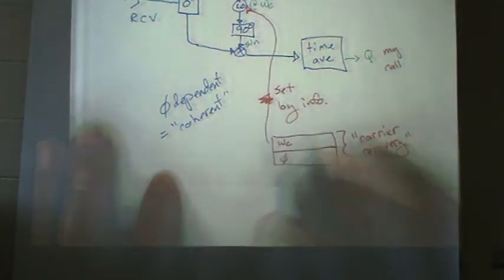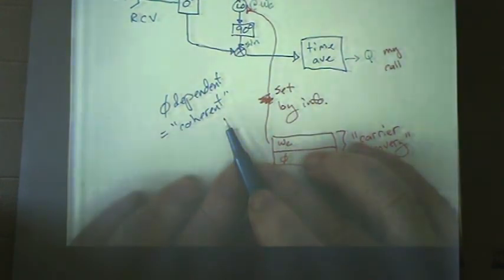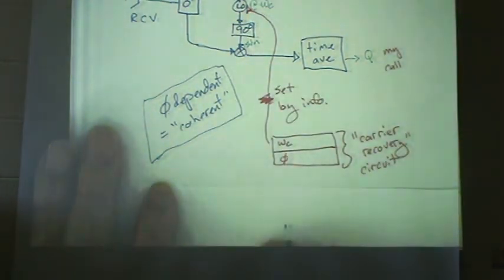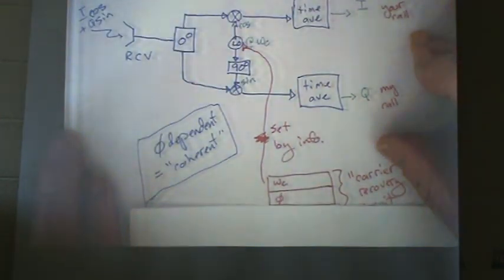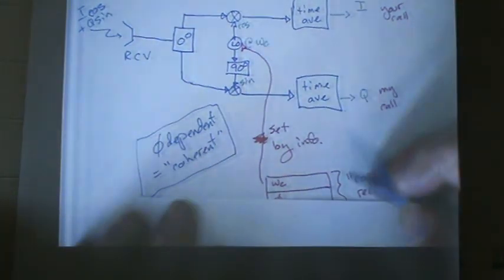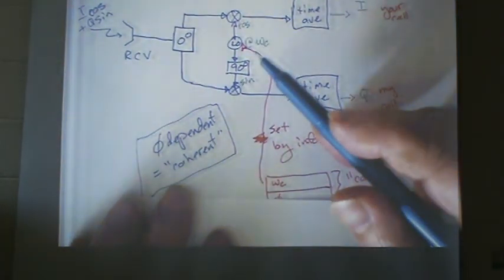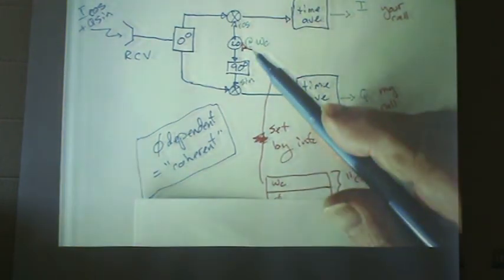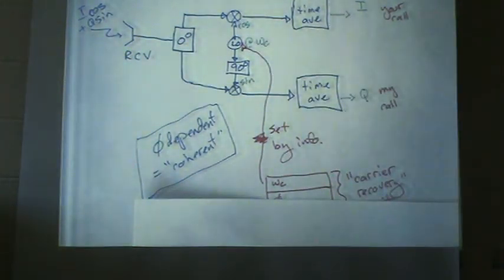So when you talk to Ciena and they're trying to sell you some coherent, this is the latest, greatest thing. That means it's some type of phase-dependent modulation scheme. QAM being one example that I've drawn out here in great detail. Phase shift keying obviously depends on the phase too, right? So there's got to be something that sets an equivalent phase of my local oscillator in a PSK system as well.